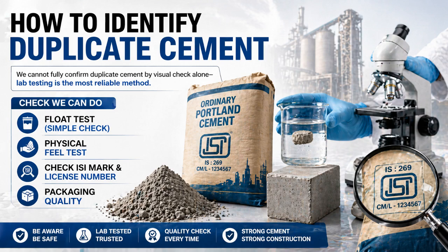It is always better to check for the ISI mark and a valid CML license number from the Bureau of Indian Standards issued to the manufacturer, and inspect packaging quality, as original bags have clear printing while fake ones often show faded colors, spelling mistakes or poor stitching. In addition, verify the manufacturing date and batch details for traceability, purchase only from authorized dealers and avoid unusually cheap offers, as they often indicate compromised or counterfeit cement.